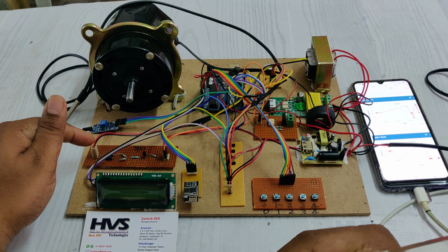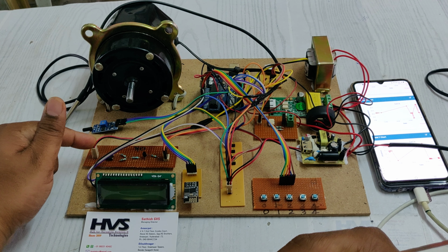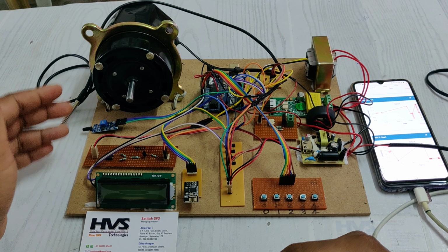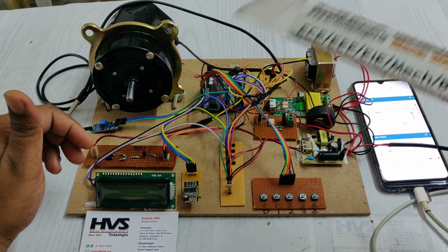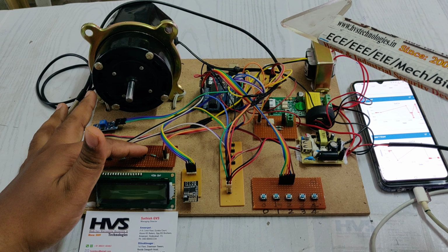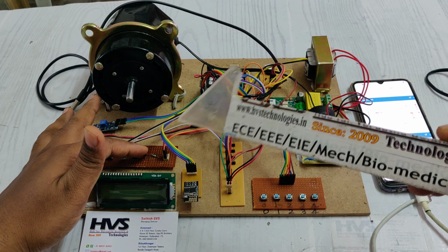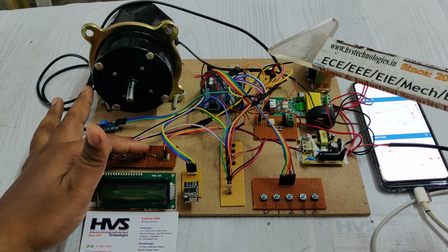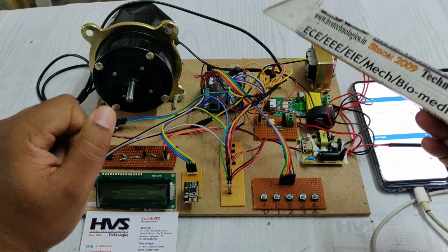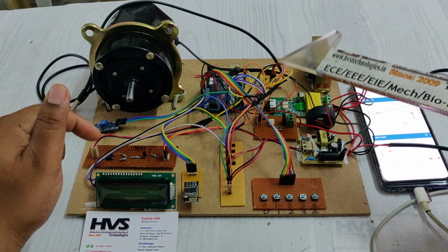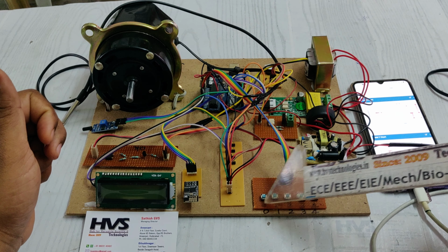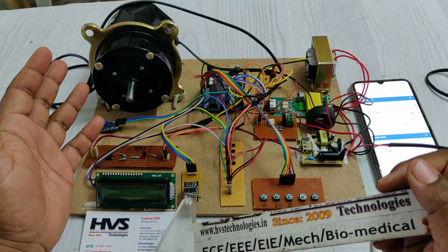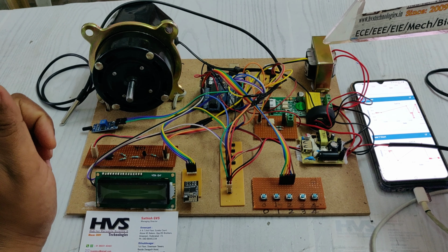Here we provide the input of 12 volts AC, and this is a DB107 IC, which will convert the AC to pulsating DC. Whenever the pulsating DC pulse is starting, and the voltage crosses 0, meaning whenever it is greater than 0.7 volt, the transistor will get triggered and the same signal will be given as input to the Arduino Uno board. Then, based on the user inputs, it will control the on time signal, so that we can control the speed of the AC induction motor directly. So that is the purpose of this transformer.